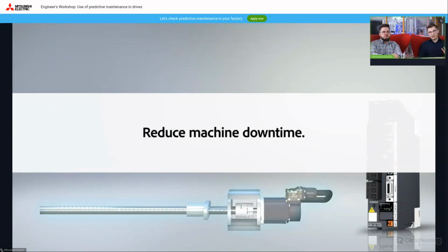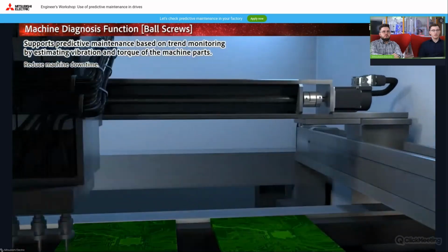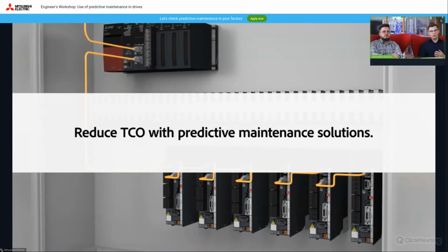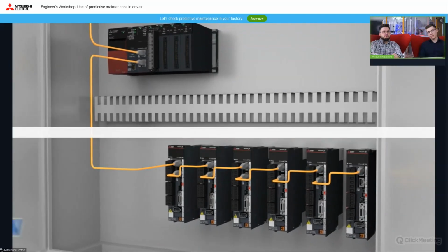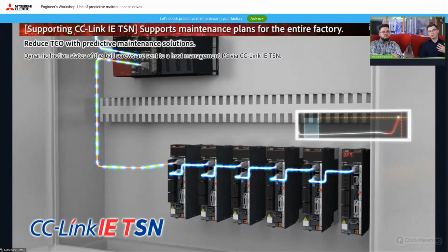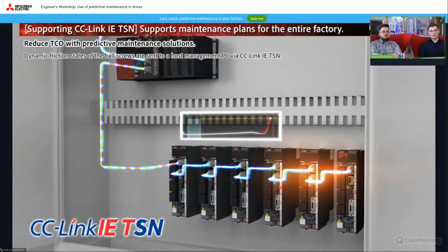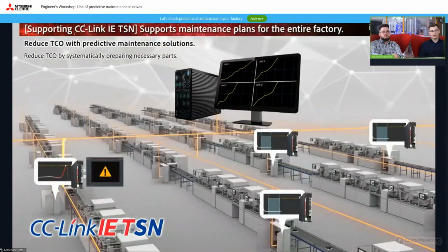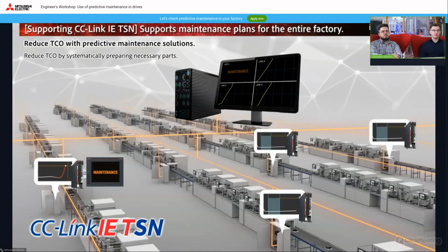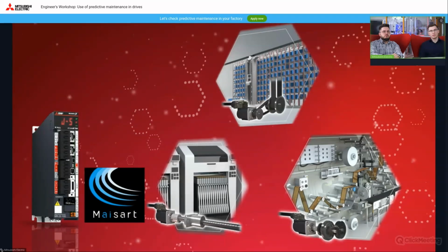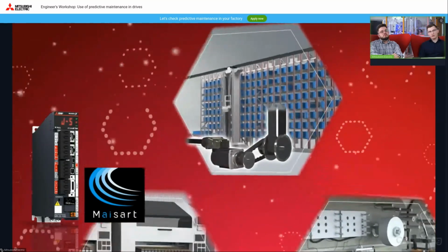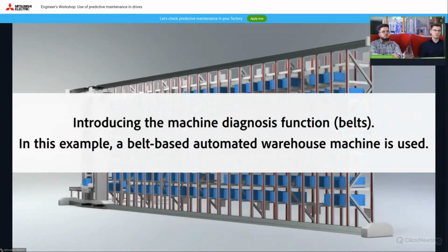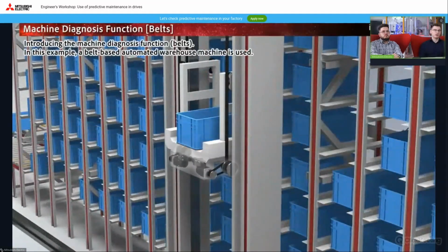Of course, this alarm will not stop the normal work of the servo drives, but it will just be information that we can, for example, send via the network, via CC-Link IE TSN or EtherCAT to a SCADA system or HMI panels, and the operators can see the alarm in the history, and then replace the parts or just do maintenance on these parts during downtime.